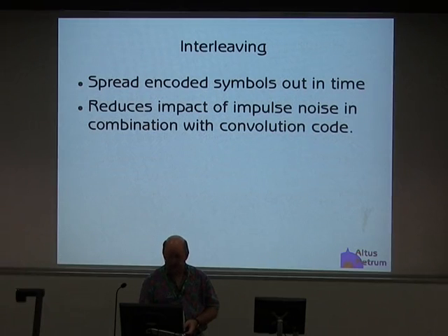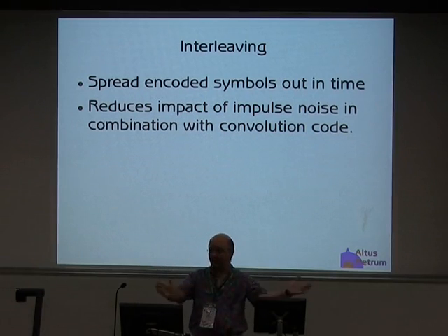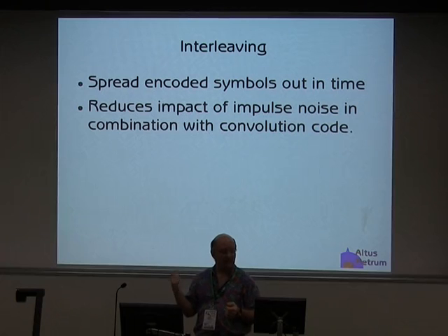There's one more thing I'm going to talk about, interleaving. Why do we do interleaving? The problem with that Viterbi decoding and the Trellis diagram is if you smash a whole long sequence of bits in a row, it can often just get totally lost. If you smash more than the constraint length of the code, you will probably never recover. And so in my k equals 4 code, if I smash 5 bits in a row, I probably won't get that packet decoded.